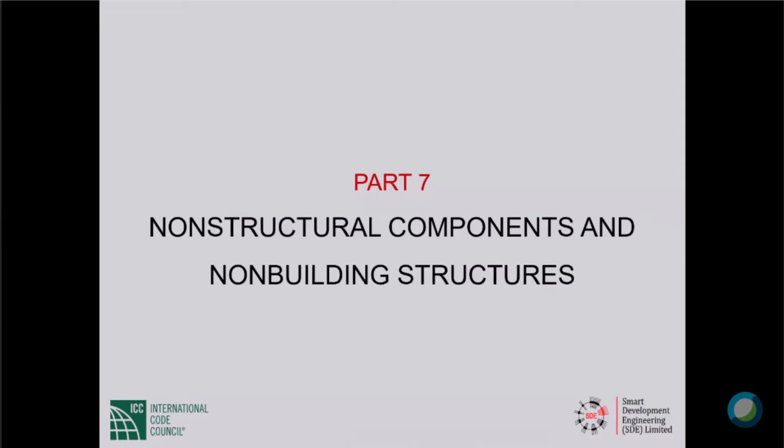The word spectral, very, very briefly: the spectral displacement is the same as maximum displacement of a structure, specifically a single degree of freedom system, which means only one component of motion of one mass is possible. You see, it gets intricate in a hurry. So spectral displacement is the same as maximum displacement. Spectral velocity is actually spectral pseudo-velocity because it is not equal to maximum velocity of the system, but very close to it. And the spectral acceleration is actually spectral pseudo-acceleration because it is not the maximum acceleration of the system, but something very close to it.